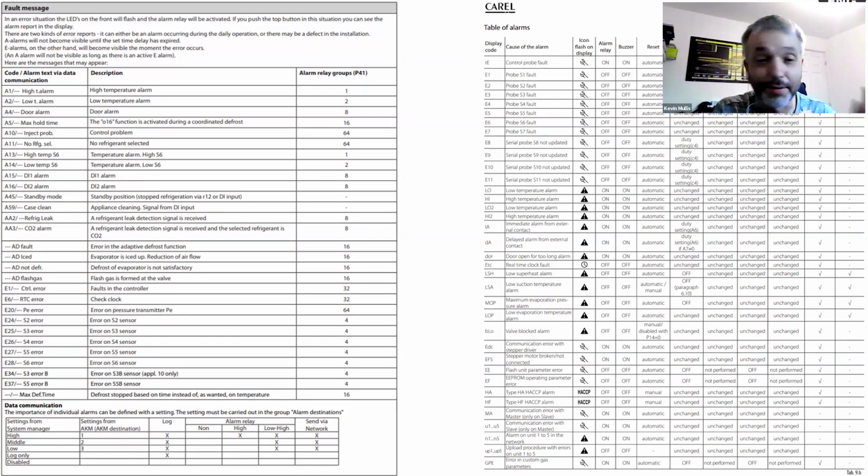Yeah, just very, very quickly, because I know we're out of time. As I said earlier, with the Carel, if you turn off the master case for the transducer, you lose transducer reading. Carel have a setting for safety evaporation temperature. It'll default to a reading if you lose the transducer, but just be really careful. If that defaults to like -10 on a lot of setups, if you're on a freezer, that ain't going to help you. Your freezer's going to break down.